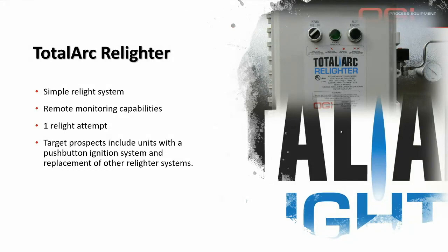Because the TotalArc Relighter works with a pneumatic flame safeguard, it only allows for one relight attempt. We ignite the spark for a time of 15 seconds. If during that time you don't have a flame, there might be other issues that you need to check. We focus our prospects for the TotalArc Relighter on upgrading basic, even simpler systems that only have a push button ignition system, and on the replacement of other manufacturers' relighting systems.